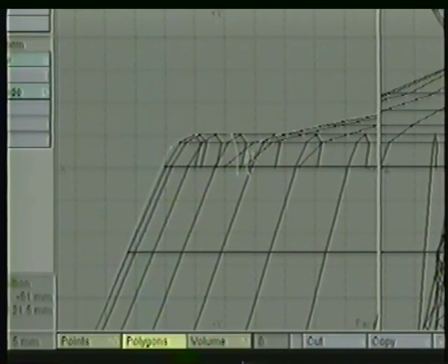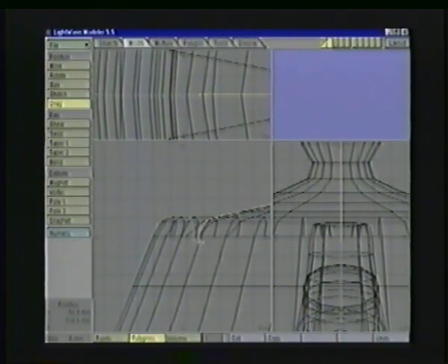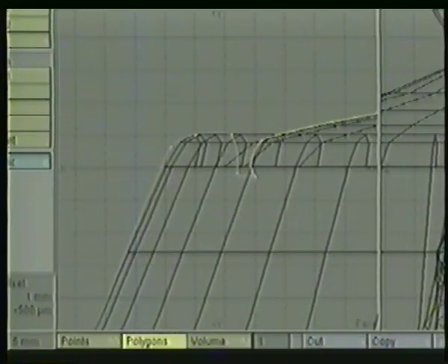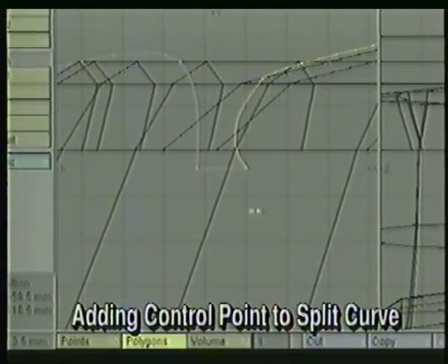Now the next thing we're going to do is select the spline that makes up the lid. I'm then going to use the modify drag tool, and you can see if I drag this, it's dragging the whole entire thing, both splines, because they're connected here. Well, that's a little bit of a problem, because what I want to be able to do is pull this one curve down, much like we did on the top of the handle. I want to add another control curve in here.